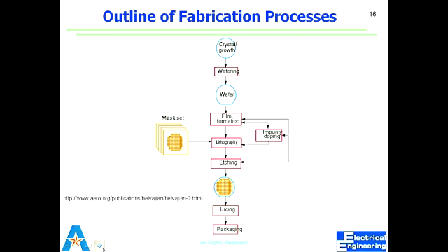Once you do lithography, then we might be doing doping, we might be doing etching, whatever. After we do one step, we keep on going to the next, until we do all the masks and we are done. Then we go to the next level where we have the whole wafer ready. Now we dice it. Dicing is cutting it into small pieces, making dies out of the whole thing, and then it goes into packaging. Packaging is something which we will not do. We will look at some aspects which may be important for front-end integration, but we will not go into the details of packaging.